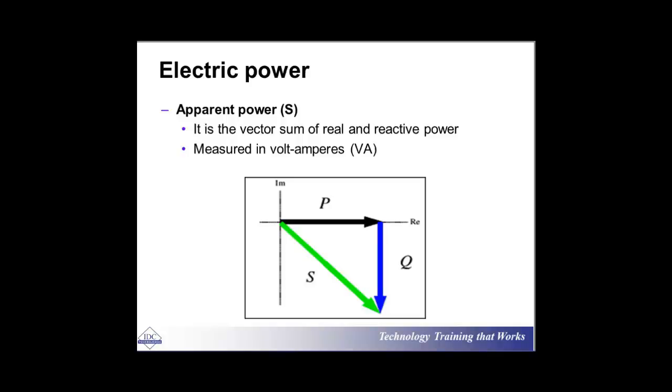And who in this class knows in what way you can correct your power factor for the power company so that you are not punished, you are not charged, you are not receiving any fine? Who can say a very common way that we use in industry? Yes, Hector, capacitors. We have got cap banks, capacitors to be connected to our loads. You can write down for yourself that when we have capacitors in place, they will inject Q to the system, so that the power company is giving you P and Q.